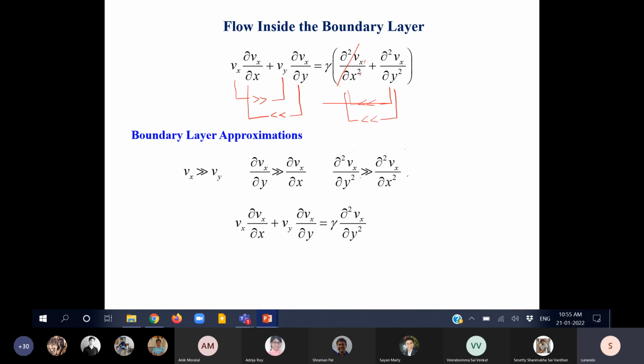We also understand that in order to obtain the shear force, we need to find what is the velocity gradient. Because if it's a Newtonian fluid, then that shear, which is drag, would be minus mu times del Vx del y, evaluated at y equal to 0. That's the shear. And you multiply that with the area and you get the expression for the shear force. So everything hinges on finding out the expression for Vx and how would it vary with y and so on.